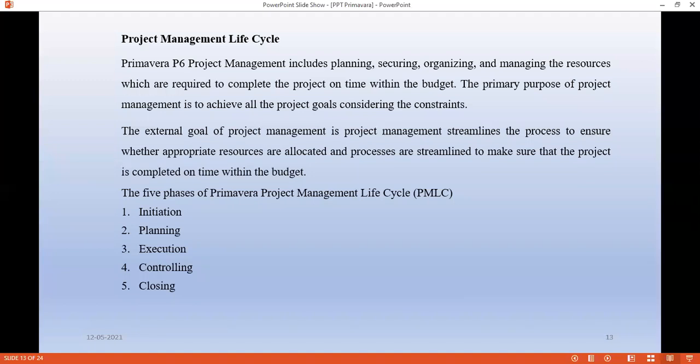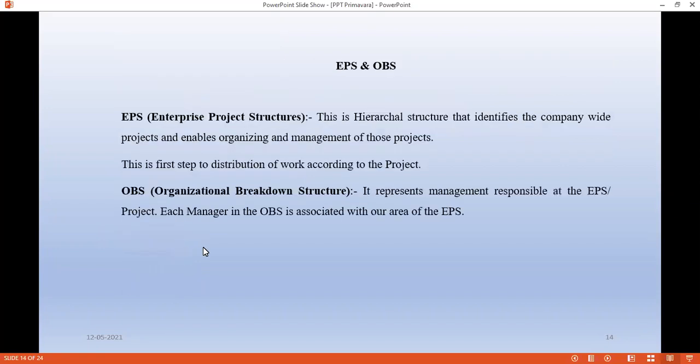If you want to execute tomorrow and you send it today, it is difficult to manage the manpower, material or equipment for the engineer working under the execution part. So you should send the schedule 15 days or even 1 month before, so that you can plan as per the requirements for the execution, whether it is material, manpower or equipment. If you require them, you will manage them, so you will manage what is required for that particular activity on the day it is to be executed. That is the third phase, the execution phase.